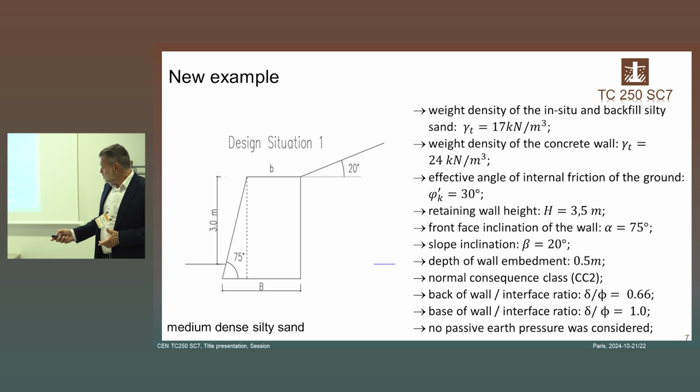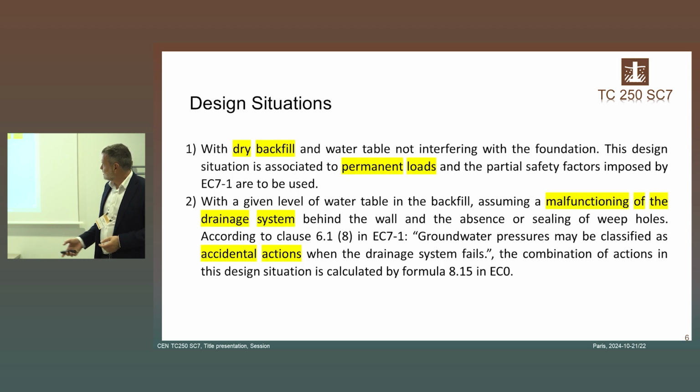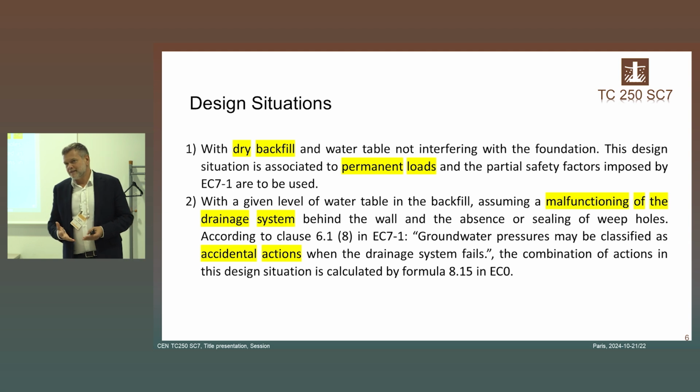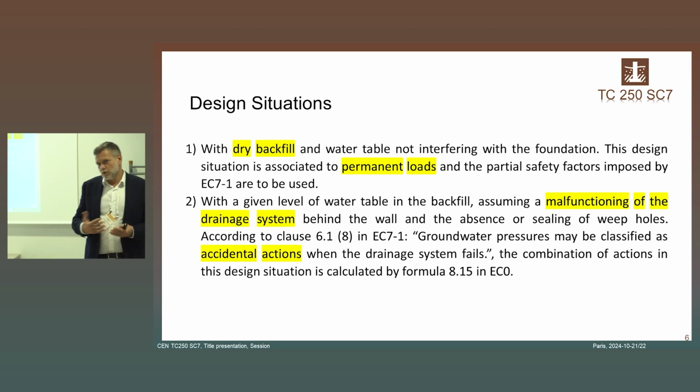And also we considered that typically a good practice is to design the drainage system in such a way that we do not have the water table in the backfill, especially because it's a permeable backfill in this case.